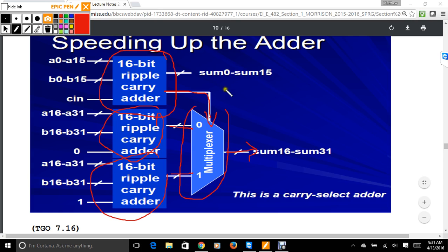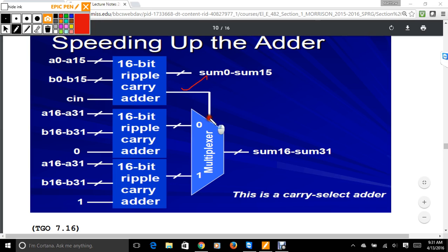Again, with these design rule checks, you checked a cell, then you check the 16-bit cell within that to make sure it works. Then as you go through this level of the hierarchy, you're just checking the multiplexer and these wires to make sure everything works. All this is meant to reduce the time necessary to synthesize.